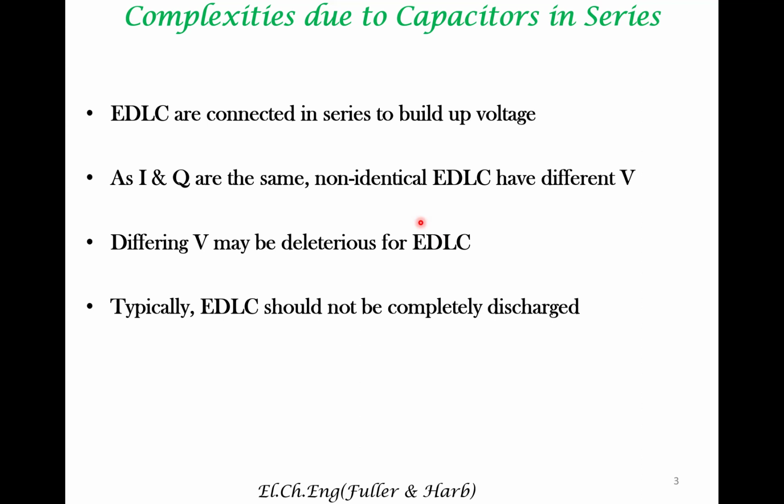While this might be a lesser problem for a capacitor compared to a battery, as the structural changes that occur during the discharge of the device are lesser in the case of EDLC, you still do not want to be discharging the capacitor to the full extent. Therefore, you typically operate between 40 to 80% of maximum potential rating. So you do not want to be discharging. That is the main take-home message.